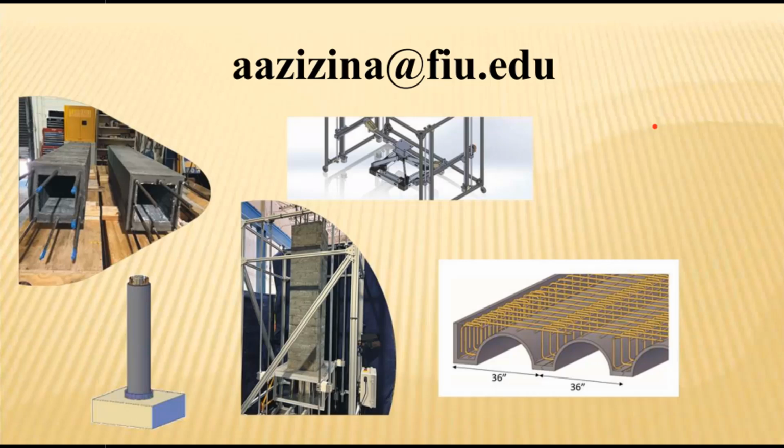Okay. You had mentioned previously the poor adhesion between dried UHPC and fresh UHPC. How is the phenomenon avoided when, for instance, the beam shell and the UHPC is poured into the shell? Up to very maximum load capacity, you do get friction, and if you put some deformations in the shell, you do get up to about the high maximum capacity. You do get pretty good connection, but at some point it breaks off.